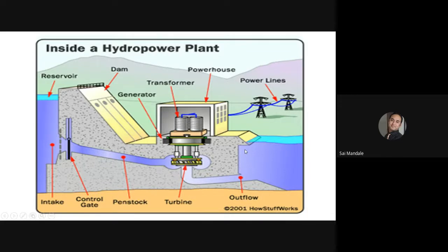But every turbine is restricted by its specification. Specification means we can rotate the turbine at a specified speed only. So even though the turbine blades can rotate at 30,000 RPM, we do not require that high an RPM. In order to control its RPM, we have to control its motion. The motion of that turbine has to be controlled through the flow, or the discharge, of the water, and that is controlled by the control gate.